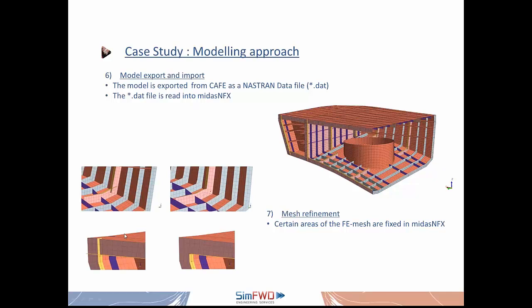So this is, let's say, an approach of very quickly meshing your initial structural design, without taking any precautions on the connections of the meshing. So we leave that behind, and we do it later on when we import our model in Midas NFX.